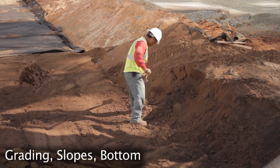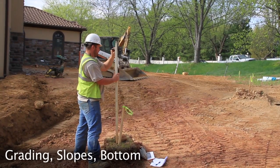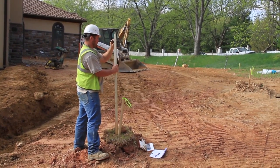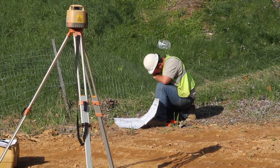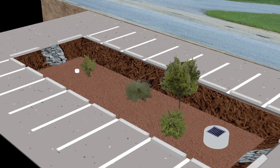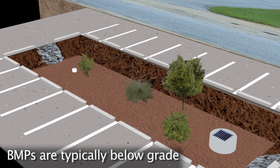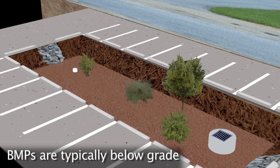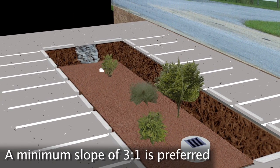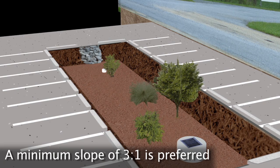The next step is proper grading. Site grades, slopes, and the condition of the bottom of the practice are critically important to ensuring the BMP functions appropriately. At this stage, it is important to ensure that water has positive flow and enters and exits the practice as designed. Stormwater BMPs are generally lower than the surrounding ground. Make sure the side slopes leading down to the practice are properly constructed. Most BMPs look to achieve a minimum slope of 3 to 1 to ensure that the slopes do not fail or contribute large amounts of sediment to the BMP.